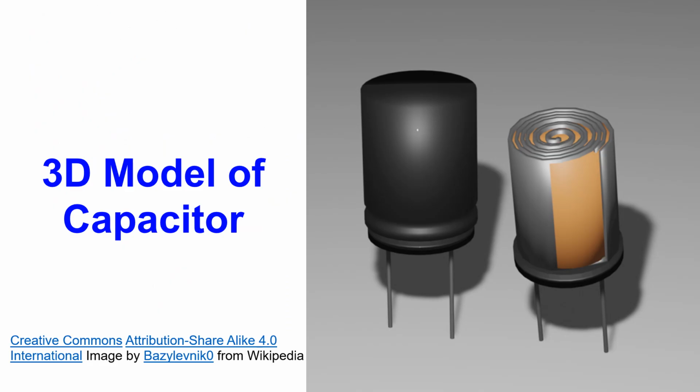Electrolytic capacitors have one plate as an aluminum or tantalum plate with an oxide dielectric layer. Second plate for an electrolytic capacitor is a thin layer of electrolyte which is connected to the circuit by another foil plate. Though electrolytic capacitors have very high capacitance, they have poor tolerance, high instability, gradual loss of capacitance, especially with high ambient temperature, and high leakage current.